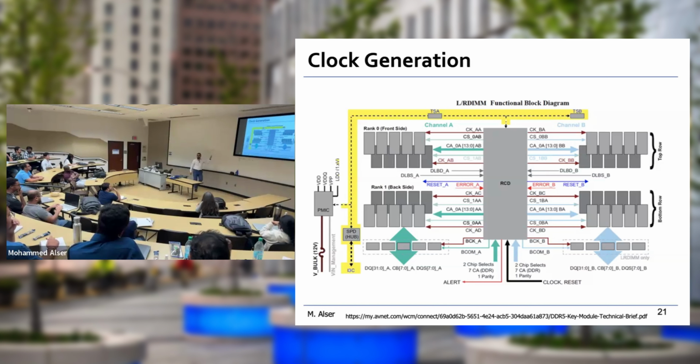And why do we talk about clocks here? Do you remember the serializer, deserializer? If you convert the 8 into 4, you go with a slower frequency, right? And now when you want to transfer the 4 into 2, you go with a faster frequency. And 2 to 1, a much faster frequency than the rest of the module. That's in the serializer.